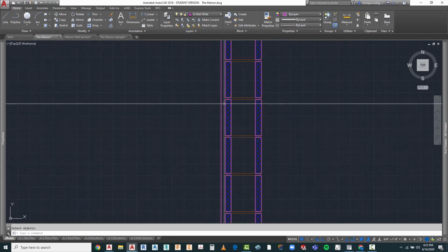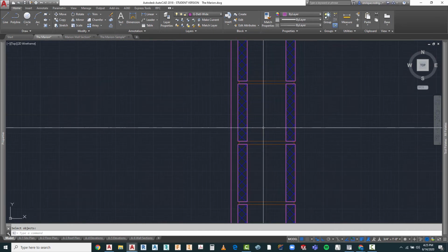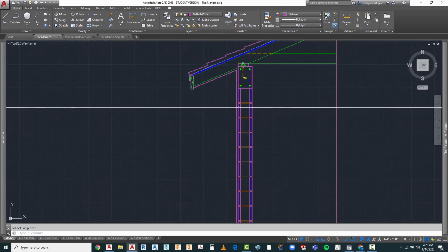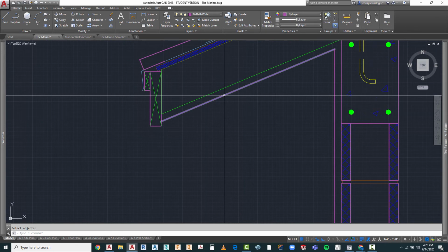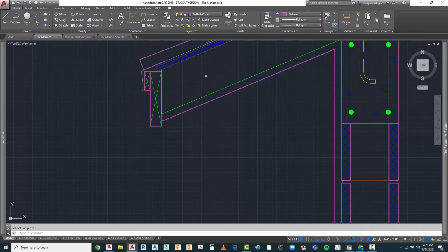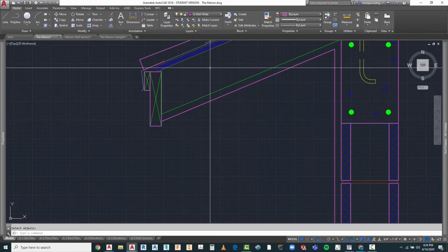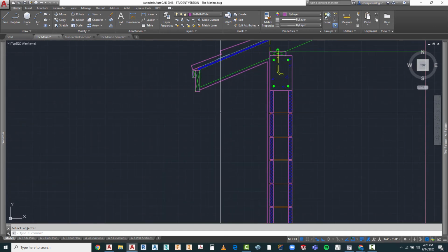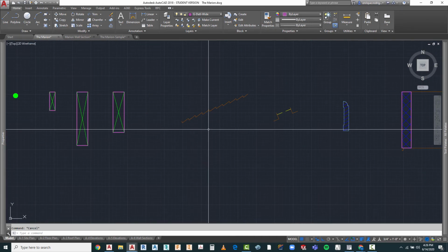Our stucco can go directly onto the block. Our block is a solid surface, and it's textured so that using the proper number of coats for the stucco, it will adhere easily. The problem here is that these rafters occur every 2 feet roughly. So how do you stucco against the air between those 2 feet? Well, we use what we call a high rib metal lath. It's a self-furring metal lath, and that element is this element that we have here.